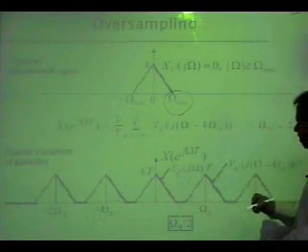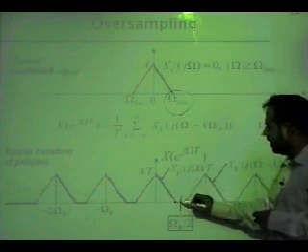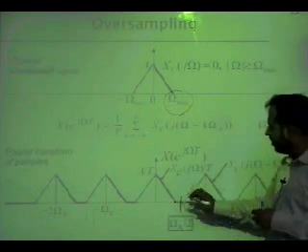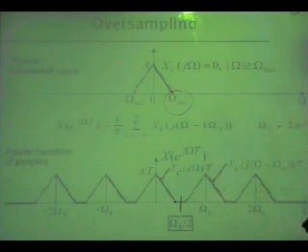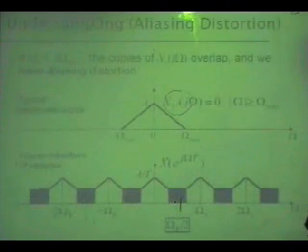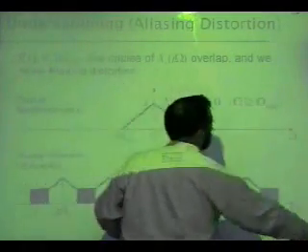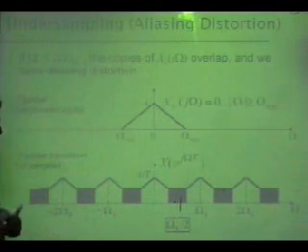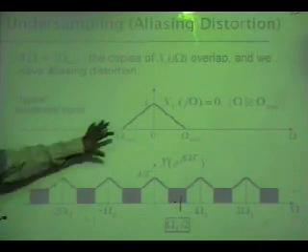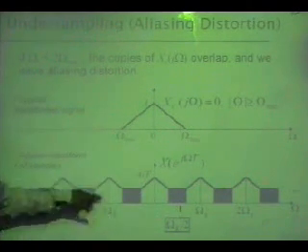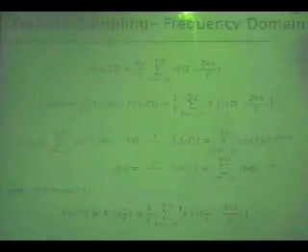And from here you know that this is half the sampling frequency, and this point must be away from this point. This is what we just concluded, and if you make sure of that, it results in the sampling theorem, that your sampling frequency must be twice the highest frequency. And if you don't obey that, there will be aliasing, so it will be corrupting part of the spectrum. So you need to make sure that you are not doing that.